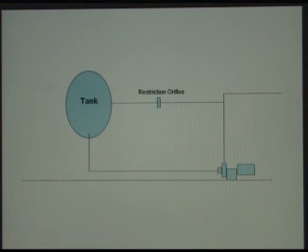The other low flow protection device would be just to have a restriction orifice, which is a continuously flowing device. So if you wanted to have 100 gallons per minute going forward for your process, if you size the restriction orifice so that it always keeps the pump at least 10 GPM, which is the minimum flow of the pump, you'd have to size the pump for 110 GPM, anticipating 10 going back to the tank and the 100 going forward for your process. It's a nice passive system. You don't have to worry about it operating. It's always there, and unless somebody puts an isolation valve in there sometime, you can always rely on it.